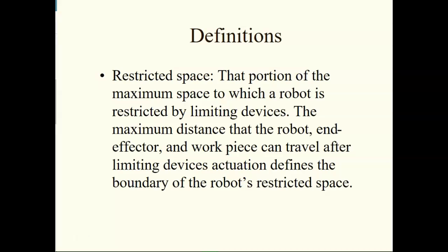So one of the things we do to limit robots is one of 2 things. One, we can limit them by putting them in a cage because they can't get out of those, right? Another thing we actually do, and this is kind of interesting for most people, is you have the ability to set, using the software of the robot, software boundaries. You cannot exceed this point. You tell it that electronically, and it just sits there and goes, okay, I can't exceed that point. You know, there's only so far I can reach. Oops. That kind of thing.